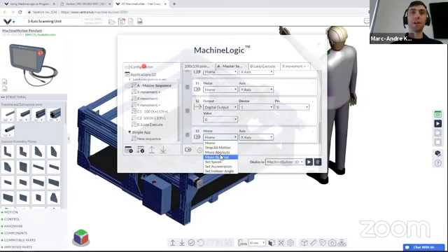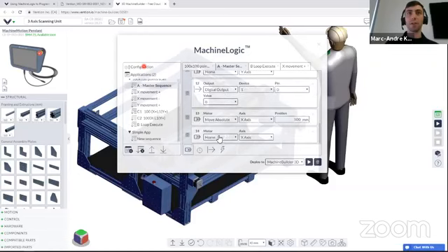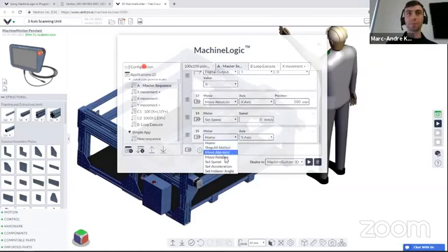But before that, if you just put it this way and change the position, let's say to 500, it's going to use the default values that we've included in the machine logic software. So it's going at the max speed and max acceleration. But before you actually put this motor step, you're going to want to set the speed and set the acceleration.